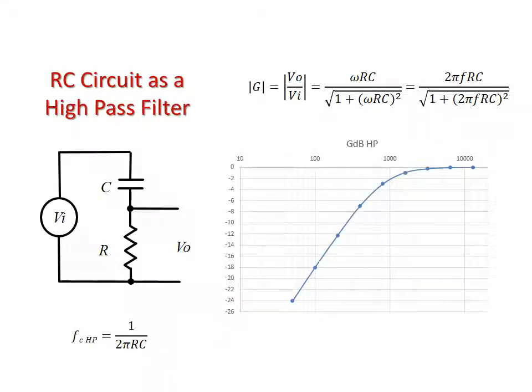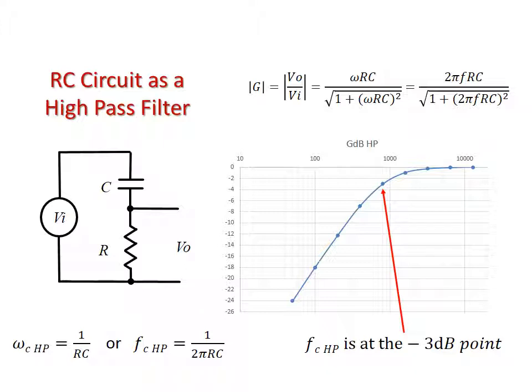So here again, we have the cutoff frequency of our high pass, equal to 1 over 2 pi RC, and we've plotted the frequency versus the gain in decibels, which remember is a non-linear scale. This way we can look at what happens. If we identify the point around 1,100, we can look at the frequency of the cutoff point. Again, this is the -3 decibel cutoff point, the same as on the other side of the circuit, when we were looking over the capacitor, because we haven't changed the capacitor or the resistor's value.